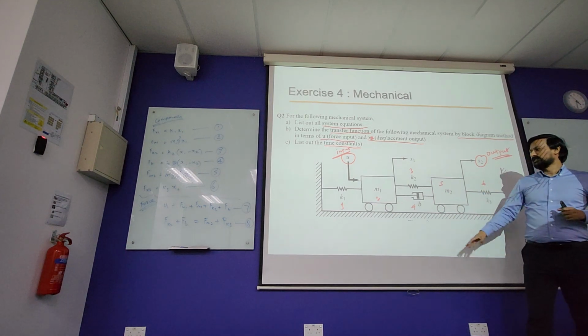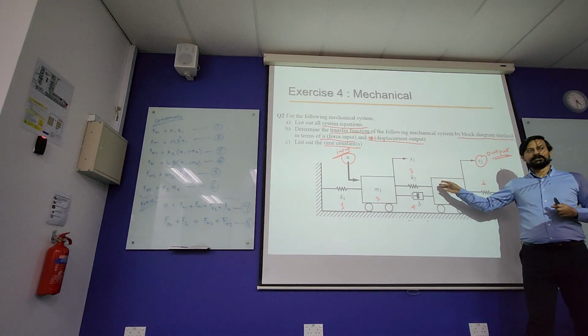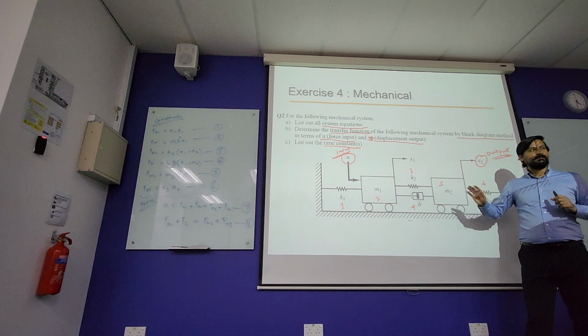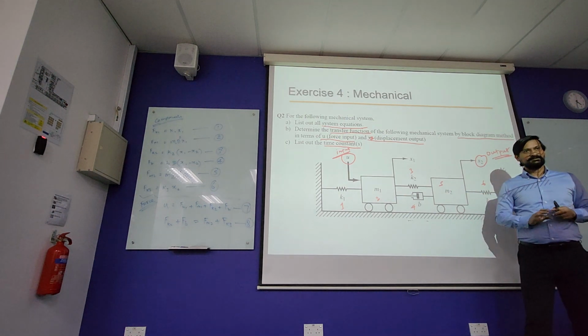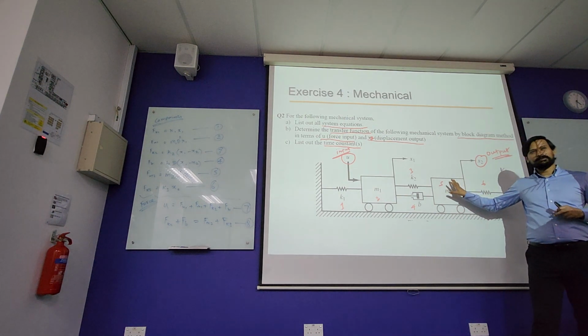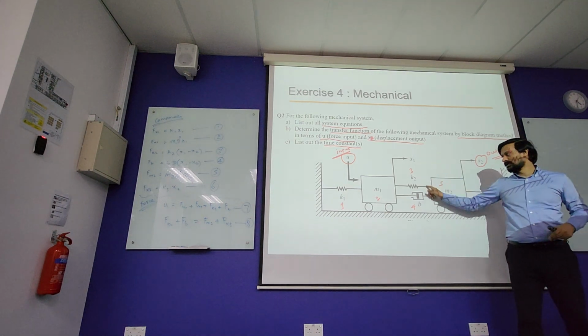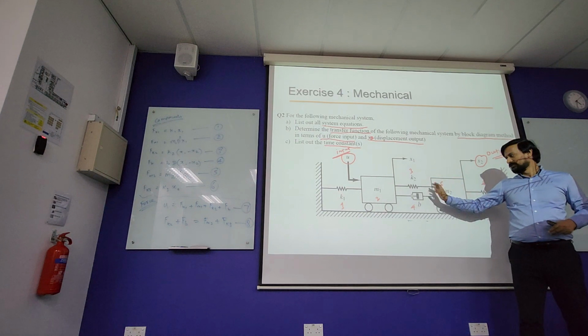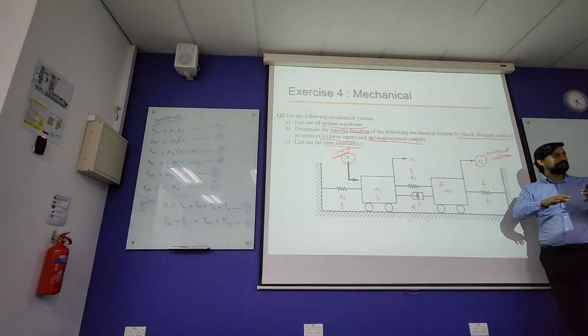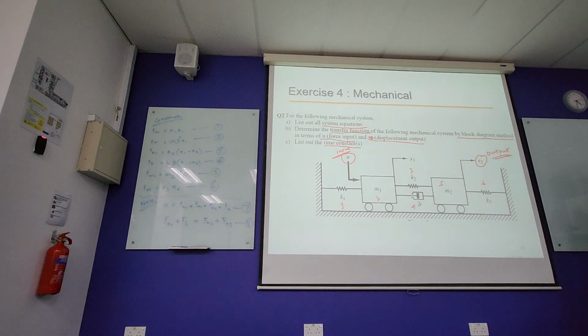In other terms, whenever there is another mass coming, we are able to stop there because mass will dampen everything. Okay, so you can have control. Whenever the mass is there, we can draw a line. I think you can draw an imaginary line over here. Then you can cut off whatever component, M1 and M2. So, M2 and K3 is like the shaft 2 of the previous question, right?